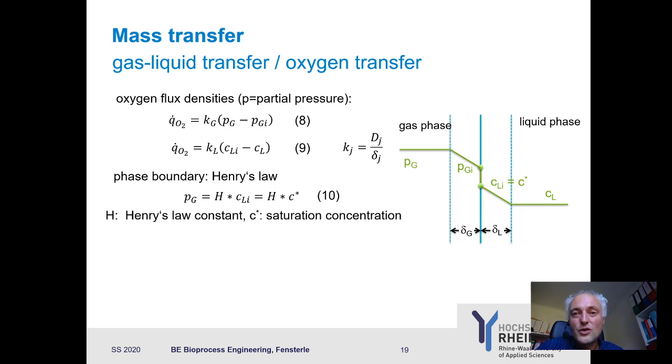And this depends, of course, on the temperature and so on, that's clear. But this is dictated by Henry's law, and this is what you know. So if you know Henry's law constant, you can calculate from your gas phase what the saturation concentration in the liquid phase is, because this comes from the equilibrium. And this Pg is your Pg here, and this is exactly the saturation concentration at the liquid phase. This is cool.